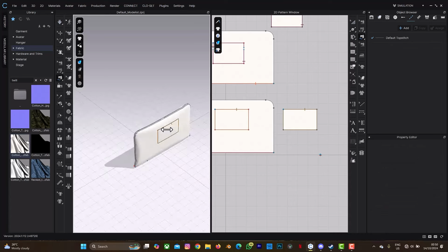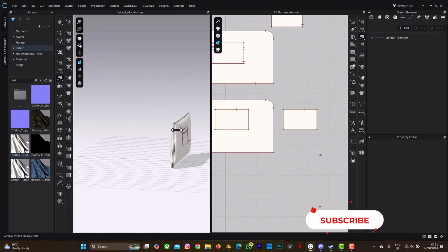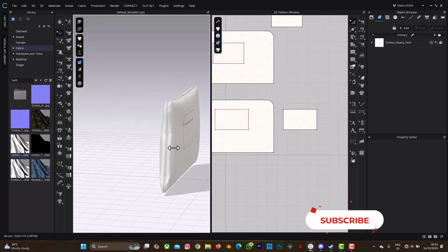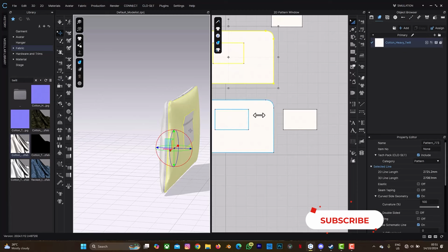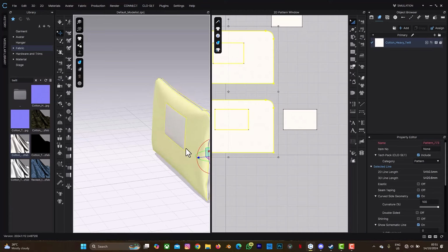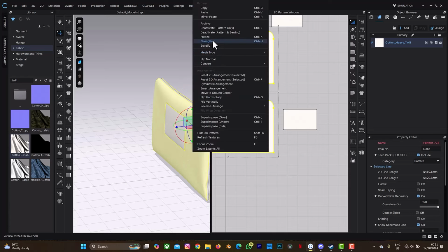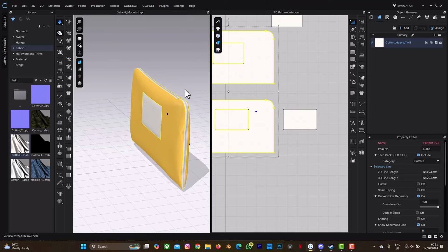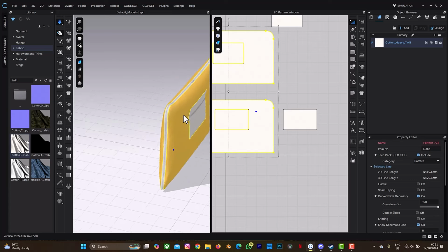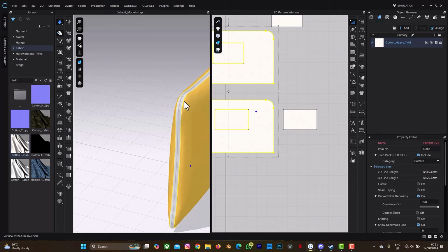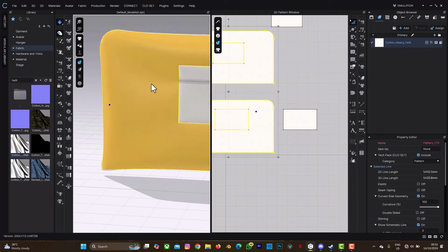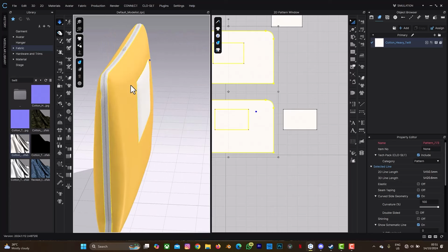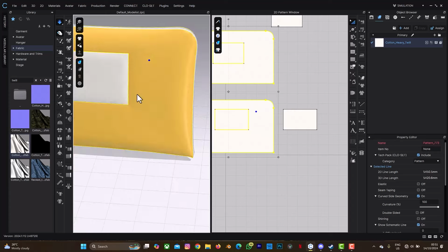So to give our design a good shape with less wrinkles, let's select Q, then select, you can just select this front and back. Yeah, select both. All you do is right click and click on strengthen, then simulate. Okay, so it might still take a while. You can see, I think it's better than that one. You can just wait for it to look good.